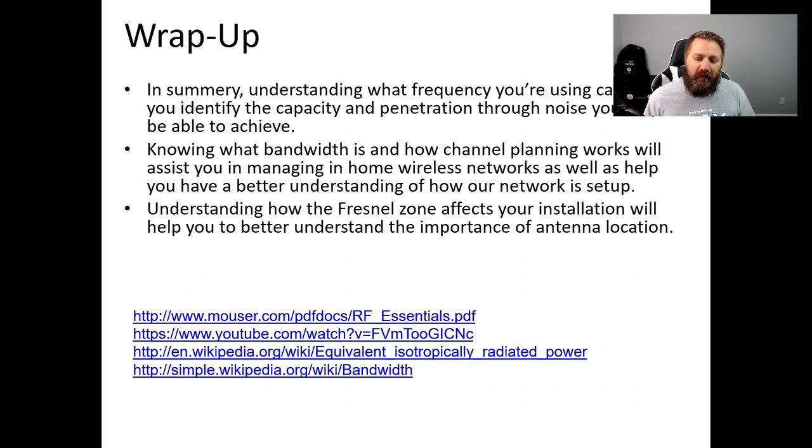So, quick summary. Understanding what frequency is obviously is going to help you identify the capacity and the penetration through noise that you'll be able to achieve. Understanding what bandwidth is will help with channel planning and setting up in-home wireless networks and better understanding of how your network works. But most importantly, in my opinion, for your guys that are going out there and doing this every day, is what a Fresnel zone is and how it affects your installations.